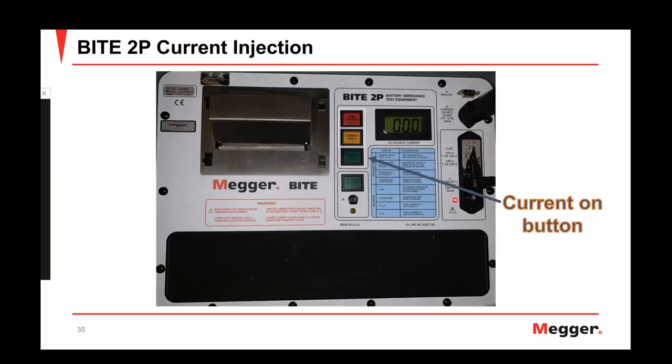What you're going to do is push that green current on button, and it's going to illuminate green. As the capacitors in the unit warm up, and we wait on that process, the yellow current ready light is going to come on. And whenever we have a current being injected by the unit, we're going to see 11 amps on the ammeter on the transmitter.